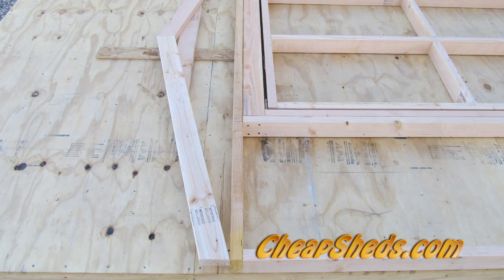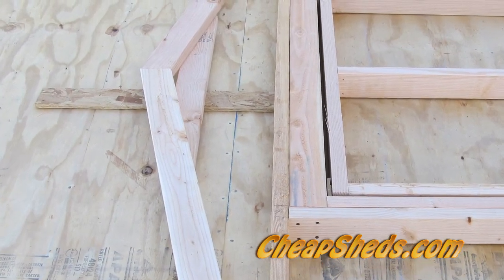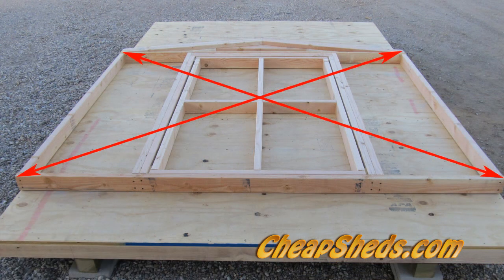For a gable end wall, install the truss with a 3-inch screw at each end and remember the ½ inch spacer below the collar beam. Check for square by comparing diagonal measurements.